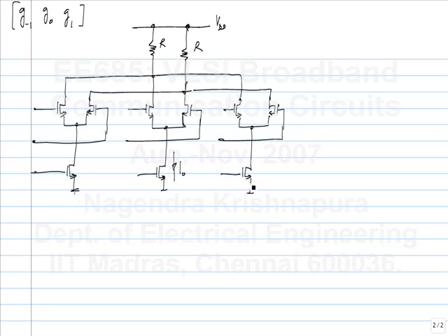So what will be these tail currents? This and this. So it's in the same ratio as the taps. Okay. So this current should be G minus 1. I am assuming that I'll apply the precursor voltage here, the delayed one here, and another delayed one here. So this could be V minus 1, V0 and V1. So V0 is delayed with respect to V minus 1 by 1 clock cycle, and V1 is delayed with respect to V0 by another clock cycle. And the tail current source in each tap is a function of the equalizer coefficient that you want to realize.